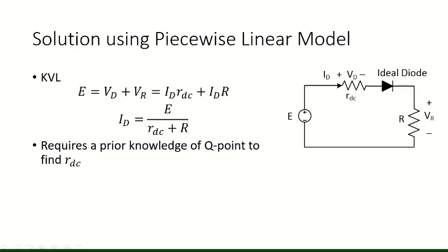And the third one is resistor. The drop across resistor R is VR, same like the previous diagram. So in this model, we have replaced the diode with a combination of a resistor, which shows the internal resistance of a diode, and an ideal diode. So these two elements, when combined, result in the original diode. So applying the same KVL equation, rise in potential is equal to drop in potential, or summation of all the potentials are equal to 0.